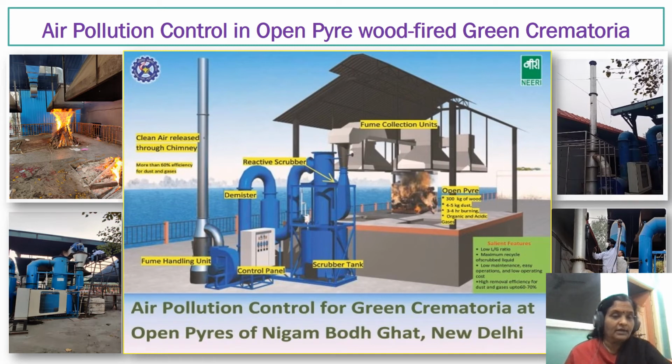The moisture laden gas then goes to the demister, which takes up all the excess moisture, water vapor and water. All this scrub liquid and excess moisture is taken to an ETP system, which treats the slurry, and the treated water is taken back to the tank of the wet scrubber.